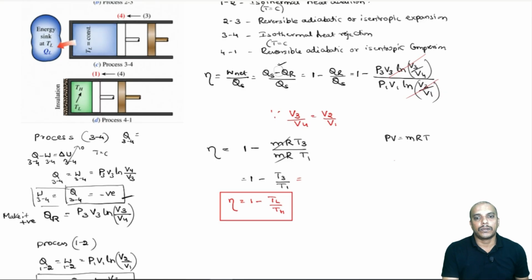All right. Whenever we talk about the Carnot cycle, remember that it is the one which gives us the highest efficiency, because heat is added at a single temperature, and it is an isothermal process. So, heat added and heat rejected, they are isothermal. One factor which makes this cycle the most efficient is that whenever we have a difference in temperature, that is the cause of irreversibility.